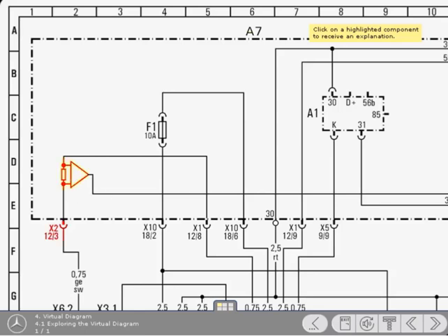This is a symbol for a bulb monitor unit. They're located in the base module, and each separate device is responsible for monitoring a specific light circuit. Each component has 3 connections. Only the lighting circuit connected to the bottom connection on the diagram is monitored by the component.